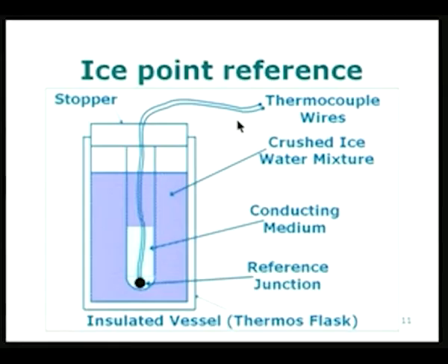So, of course, the question now is, if you have a large number of thermocouple temperatures to be measured, let us say T1, T2, T3, T4, etc., each one of them will require a reference temperature which is given by the ice point.